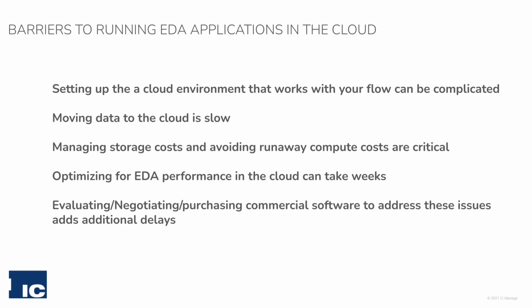Secondly, to make your EDA flow work in the cloud, you have to copy up all of your data and keep copying as the data changes so your EDA jobs are not working on old or stale data. This can take days for the first copy, and keeping things subsequently synchronized is also very inefficient and costly.